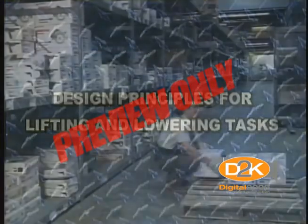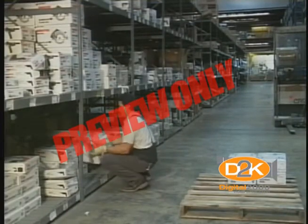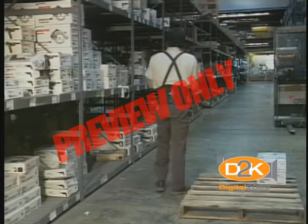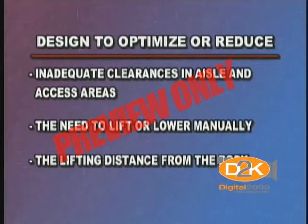It is important that lifting and lowering tasks also be carefully studied to implement ergonomic improvements. These types of tasks account for a significant portion of back injuries in the workplace. Here are some ideas that may be useful in reducing lifting and lowering task injuries. Design to optimize or reduce material flow through the workplace, manual lifting of materials, inadequate shipping and receiving facilities, inadequate storage facilities, inadequate clearances in aisle and access areas, the need to lift or lower manually, and the lifting distance from the body.